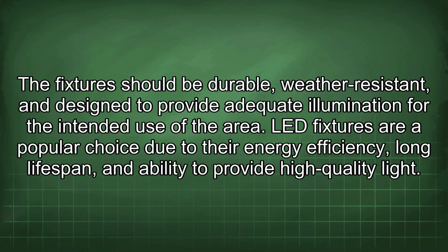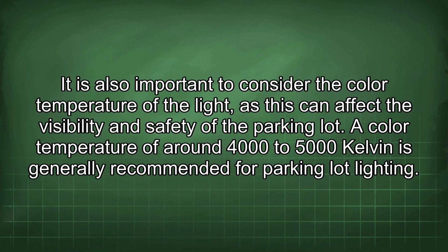The fixtures should be durable, weather-resistant, and designed to provide adequate illumination for the intended use of the area. LED fixtures are a popular choice due to their energy efficiency, long lifespan, and ability to provide high-quality light. It is also important to consider the color temperature of the light, as this can affect the visibility and safety of the parking lot. A color temperature of around 4000 to 5000 Kelvin is generally recommended for parking lot lighting.